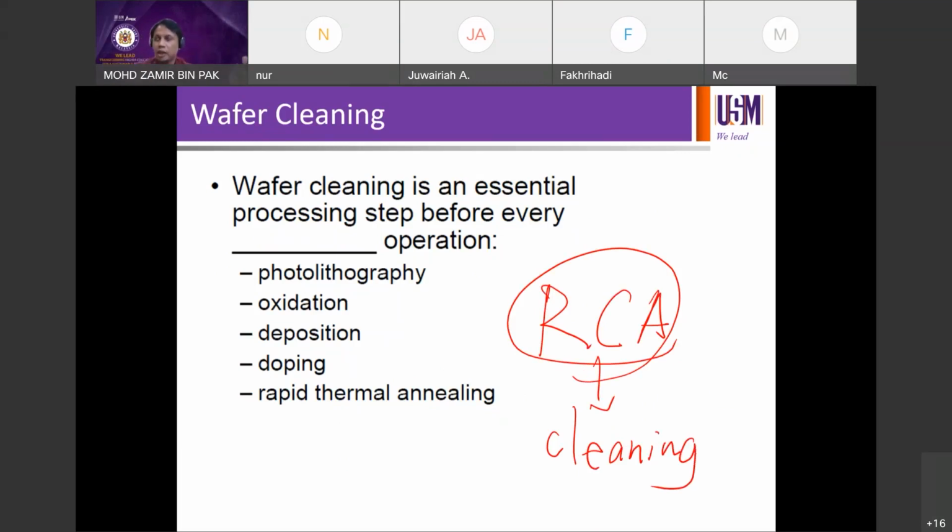You have to remove the oxide, impurities, and organic residues, and to remove all this stuff, you have to do the etching process. Etching to remove oxide, organic materials, metals, for example. So cleaning is essentially an etching process. It's a form of etching process, but we call it cleaning. The very process that goes on in the bath is actually etching.